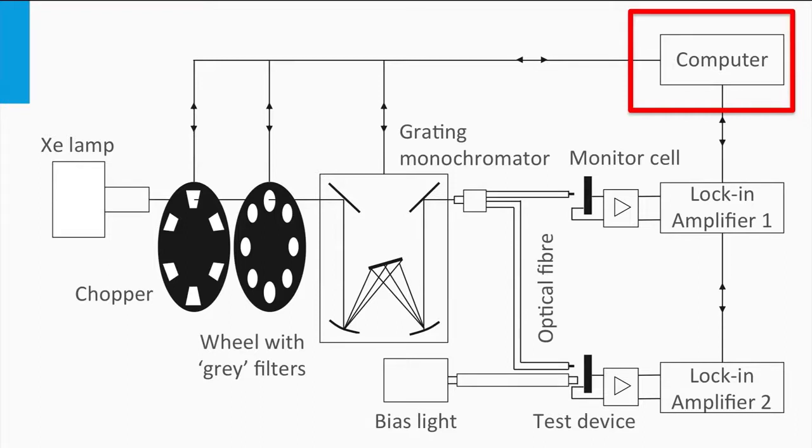The advantage of measuring the short circuit current density using an EQE setup above that of the earlier discussed JV measurements is that the current density measured by the EQE setup is independent of the spectral shape of the light source used. Secondly, on lab scale, the real contact areas of solar cells is not accurately determined.